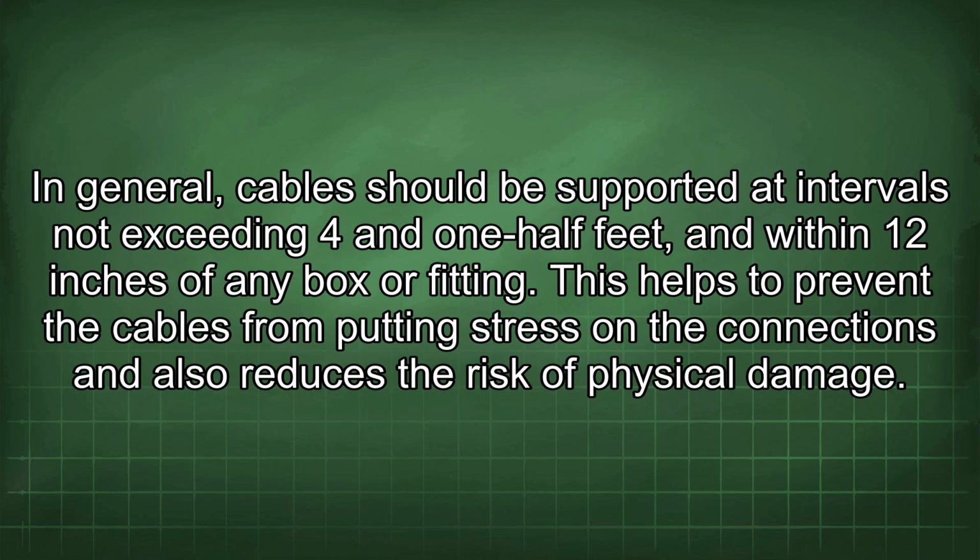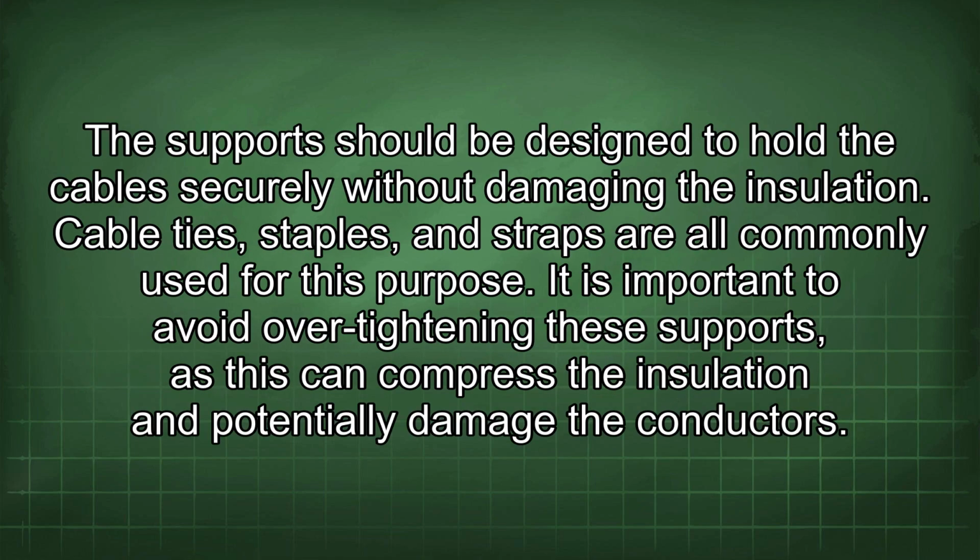This helps to prevent the cables from putting stress on the connections and also reduces the risk of physical damage. The support should be designed to hold the cable securely without damaging the insulation. Cable ties, staples, and straps are all commonly used for this purpose. It is important to avoid over-tightening these supports, as this can compress the insulation and potentially damage the conductors.